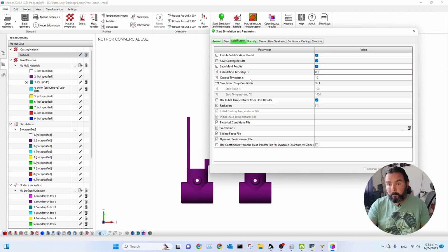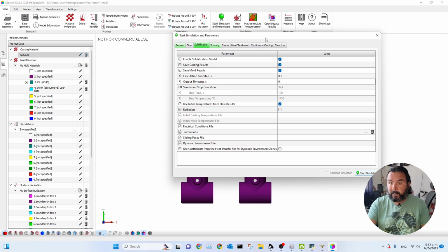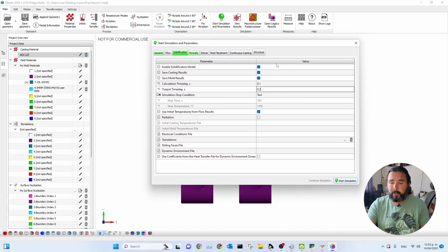The other parameter we need to set is the step at which our calculations will be saved. This doesn't influence the calculation in any way. It simply influences the number of steps we can analyze in the results analysis process. You can put the same parameter as the simulation step, but this will cause our simulation file to be very, very large. Therefore, I recommend always putting double or triple the simulation step here. And for different jobs where we are not interested in the dynamics as such and only need the final result, you can put an extremely large step here, just ensuring it fits within the calculation time.